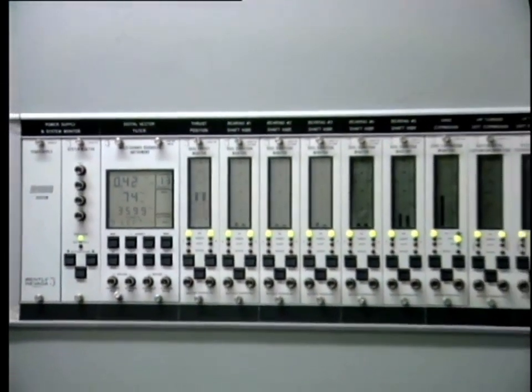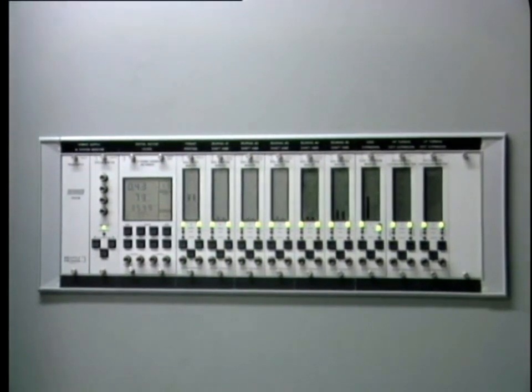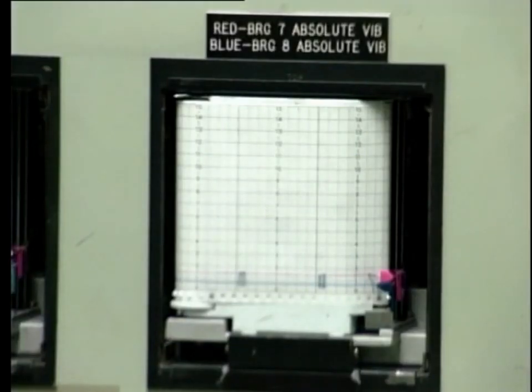It is important that the operator keep his eye on these reported levels of vibration. Any sudden change will certainly indicate the occurrence of a potential problem. For example, increased vibration on a generator bearing at a certain loading has been used to identify problems with the generator windings.